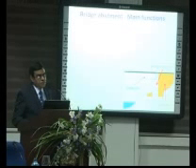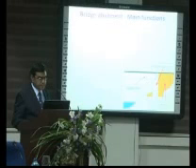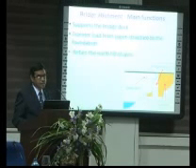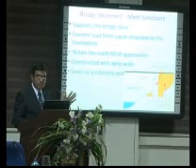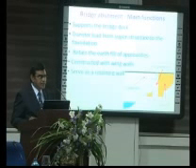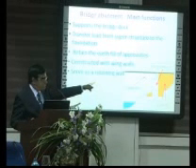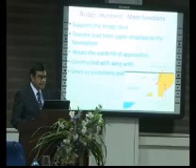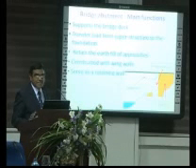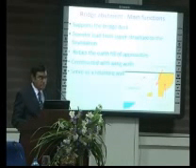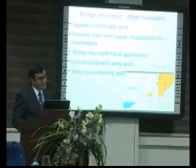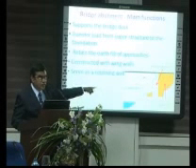So what are the functions of a bridge abutment? Let's look at the functions. A bridge abutment supports the bridge deck, transfers the load from the superstructure to the foundation, and retains the earth fill behind it. Most abutments are constructed with wing walls to support the fill material, and it serves as a retaining wall. Basically, it is a retaining wall up there, right?